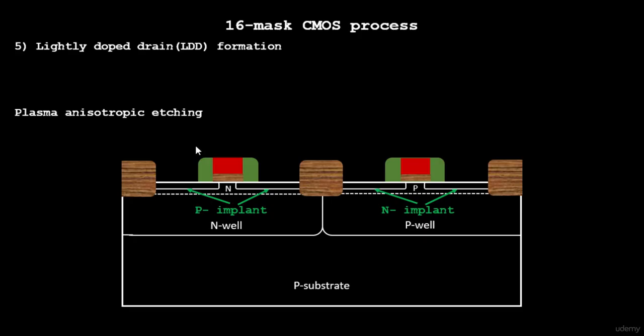In this case, you have controlled your gate voltage using your doping, using your oxide capacitances, and also made a low resistance gate by additional doping of polysilicon with n-type impurities like phosphorus and arsenic. Okay, so this is the step of formation of the gate. The next step is the lightly doped drain formation. This is again an important concept. We need certain structures of your source and drain in such a fashion which will give you the highest performance. So let's look into the next step, which is LDD formation, from the next video.